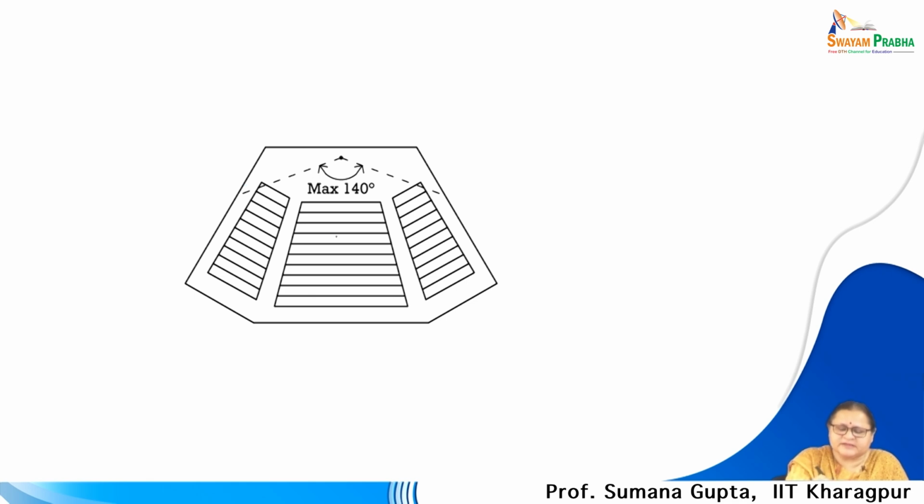So, here if I show you, if this is a plan of an auditorium accommodating a large number of audience, it is told that in this particular length there should not be more than 13 seats. So, from the central person we will have to cross 6 people either side to come out to a safe route, which is the aisle.